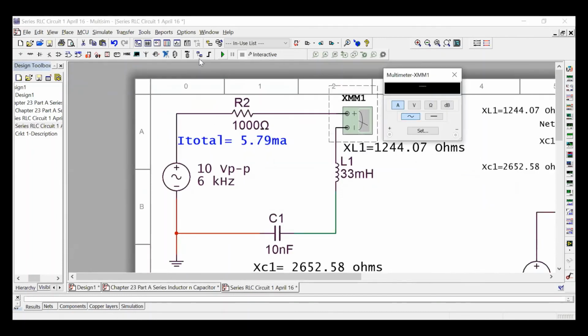So let's check to see if the current is correct at least. 2.0592. Okay, this is RMS. Check to see if everything looks good. Times it by 2. 5.82. I get 5.82, and this meter is saying 5.82 peak to peak, and we came up with 5.79. I think we're good to go on that. Anybody disagree on that?